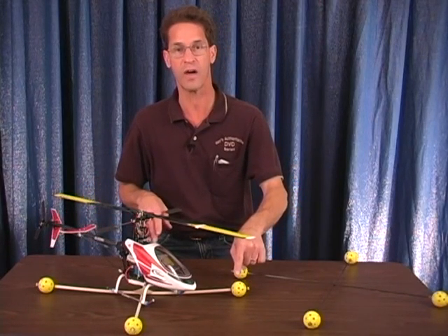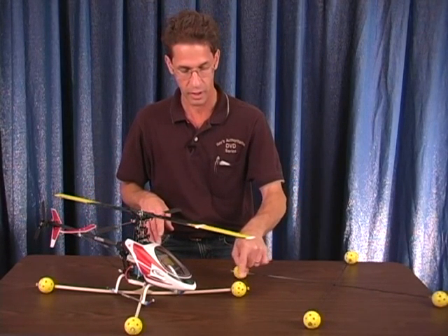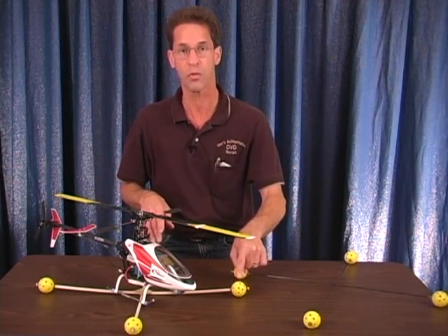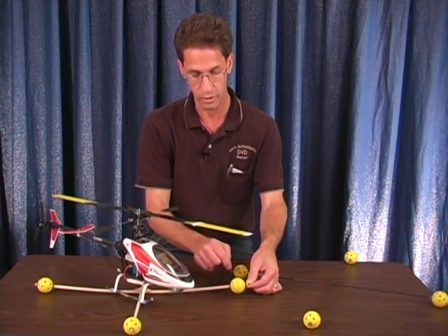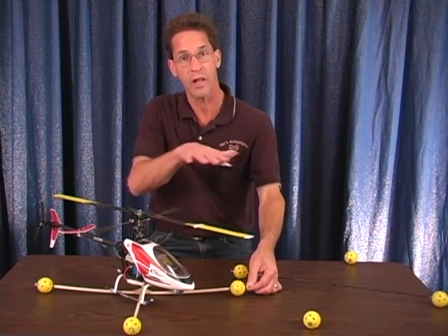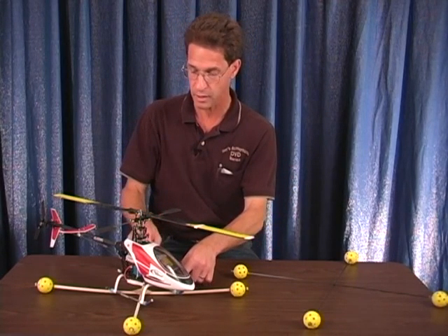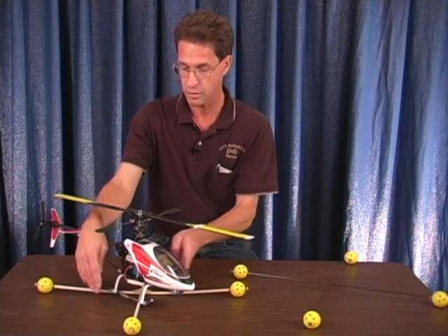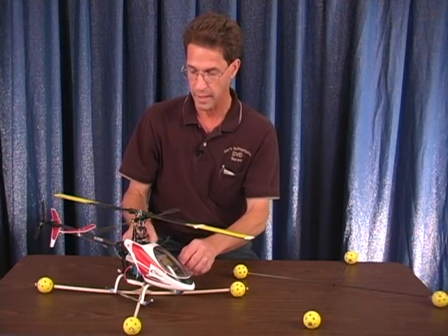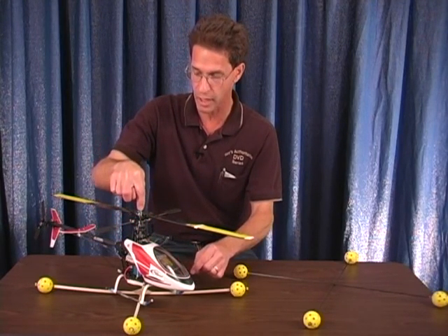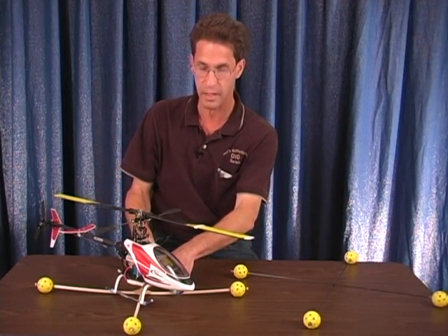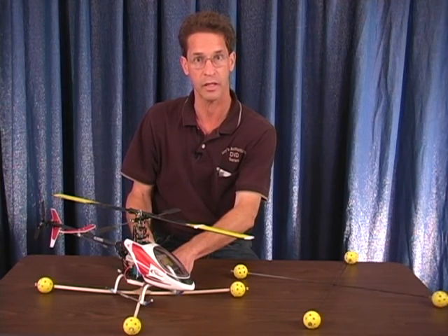Then visit your Big 5 or local sporting goods store, get some practice wiffle golf balls, and then just use O-rings to hold them on the ends. The wiffle balls should spin so the helicopter can skate on the ground. Use little zip ties to zip tie the helicopter to the training gear, and make sure that the main shaft is centered exactly over the center of the training gear.